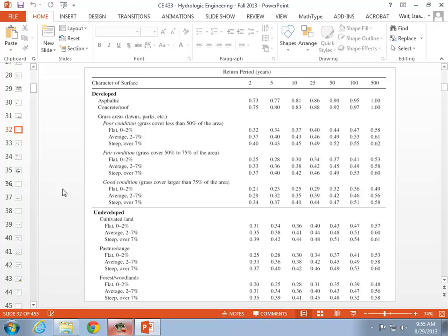So what I get is 17,860 cubic meters per hour when I use a composite C value of 0.495, 0.095 meters per hour for the rainfall intensity, and then there's 38 hectares times 10,000 square meters per hectare. So that puts this in meters per hour, this is square meters, and so the units we get out of that are cubic meters per hour. In terms of cubic meters per second, that's 4.96 cubic meters per second.